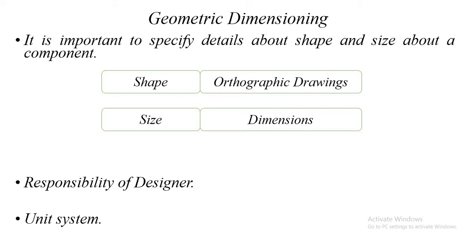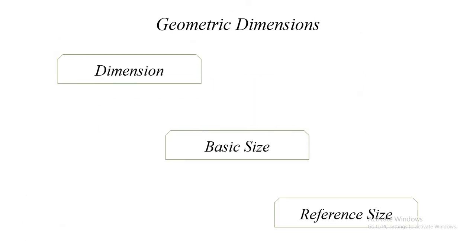The unit system used in India is millimeters in general. It is important that drawings are preferably drawn using first angle projection, as well as the statement that all dimensions are in mm is mentioned in the drawings.